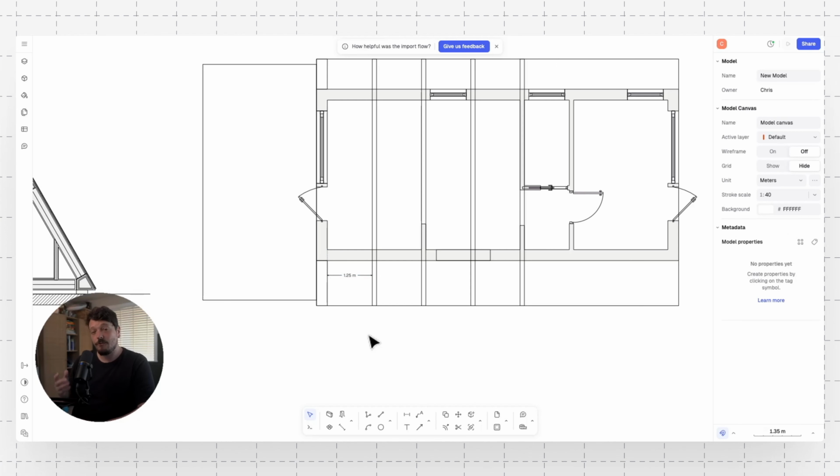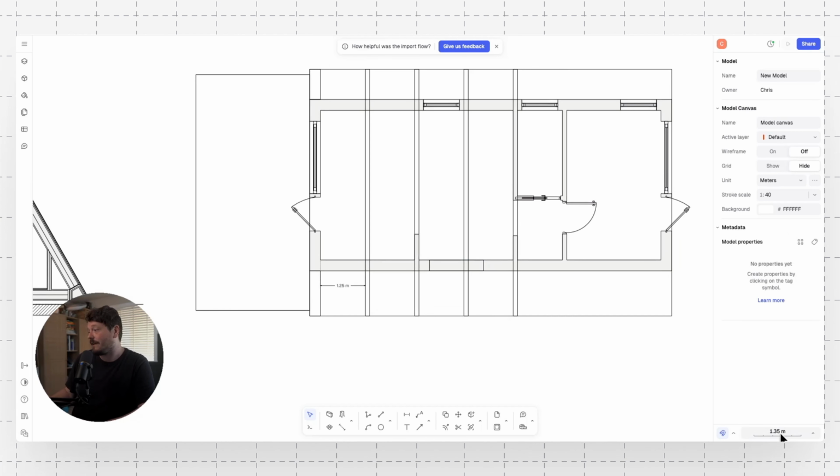Now you can alter the units in Rayon, which is really helpful. So in the bottom right hand side corner, you click on the little tab here and there are length units. So I can change that to millimeters, centimeters. At the moment it's set as meters, and I can even go to inches and feet.